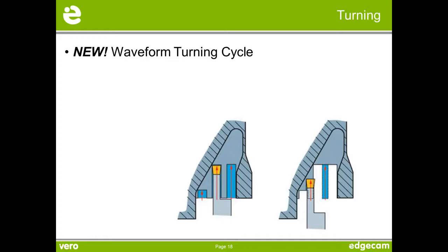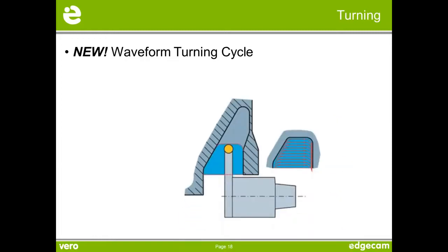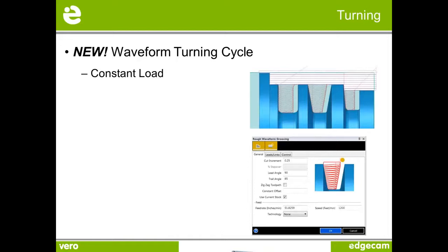This is a typical grooving cycle where we stab, where we plunge into the part, and in lots of cases Sandvik and other business partners, Seco and so on, have been asking us to produce this waveform, or trochoidal if you will, algorithm. So that's now being produced inside 2015 R1.